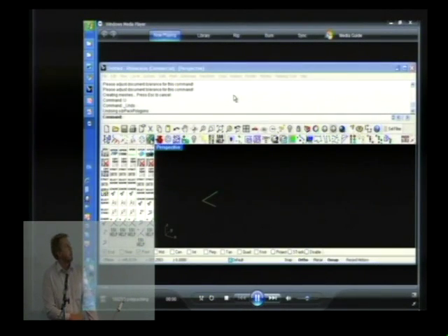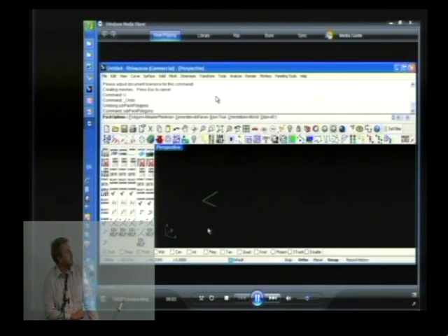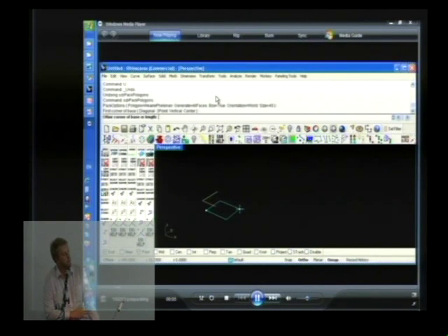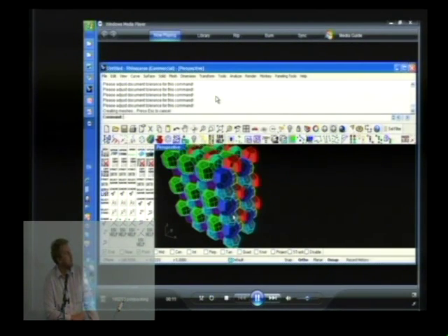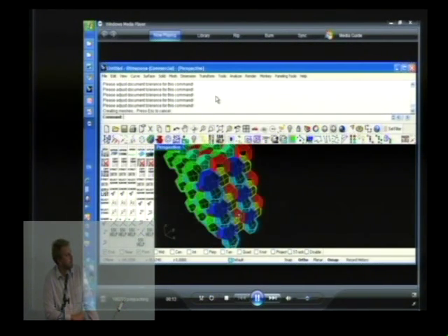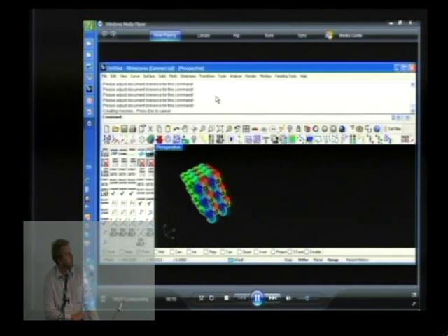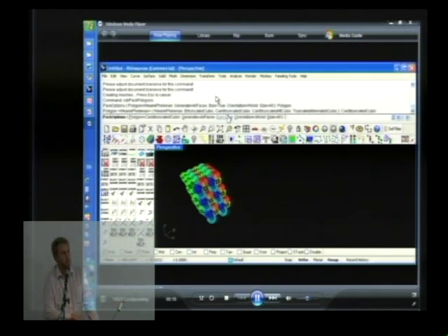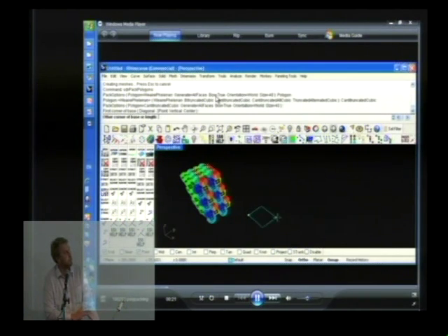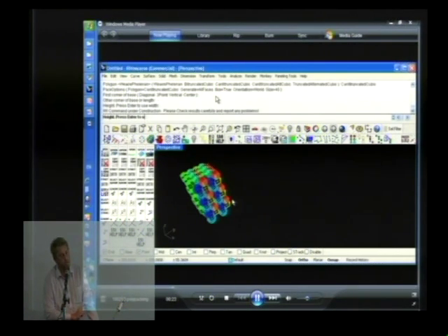I'm just going to quickly introduce a couple of other aspects for form and computational geometry type calculation that I've added in, some in response to showing examples of how other structures have been done. Tessellation or polygon packing was one of them, and I should have said a lot of these things you can download, the Grasshopper definition files etc. from the blog, which I'll quickly put the address up again at the end, and try for yourself.